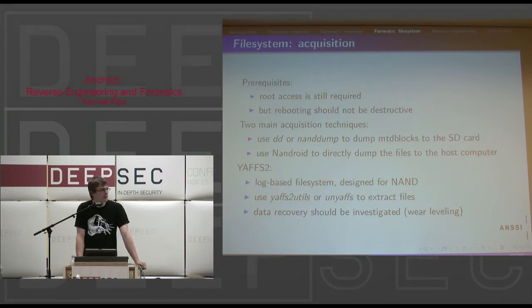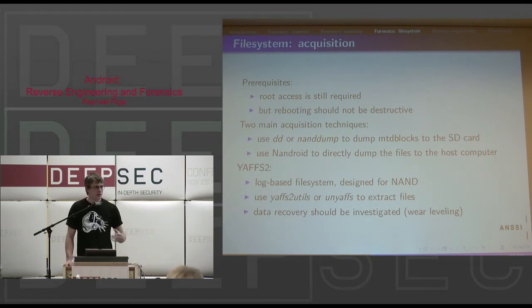I don't think so. I think these flash file systems, because erasing a block takes that long, are usually using a background job to erase blocks, so it might not be that much. Well, I've read the specification of the file system, and it could work. It depends really on the implementation, because unless you have the garbage collector running, the blocks shouldn't be erased. So I think it depends on how the file system is tuned. When does it trigger an erase because it's time consuming, and when does it stay as it is?